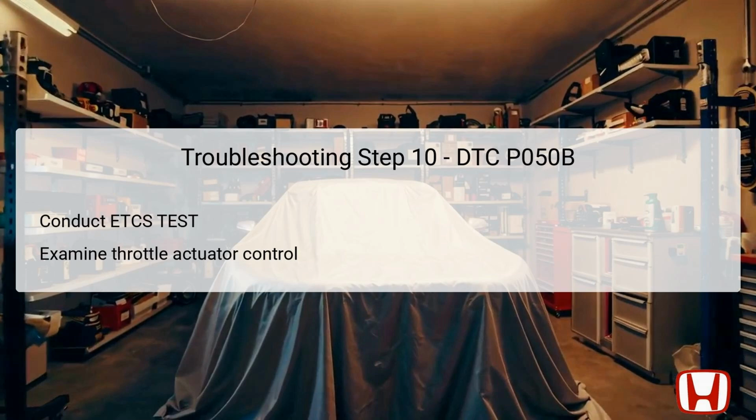in the troubleshooting process. However, if it highlights any issues, replacing the throttle body becomes necessary to correct the throttle operation. This inspection is vital because any mismatch in throttle response can directly affect ignition timing during cold starts, contributing to the code P050B symptoms.